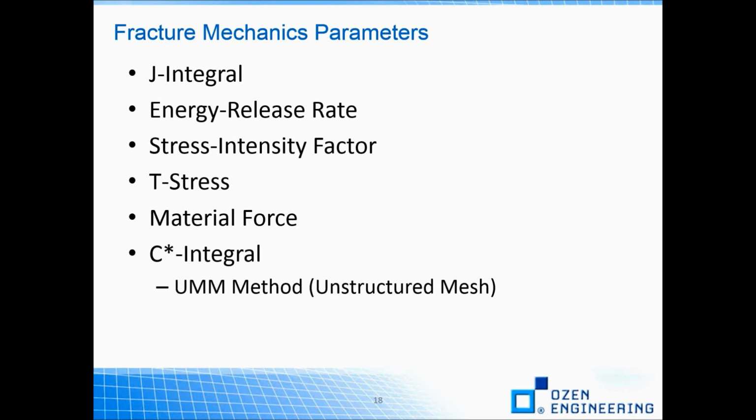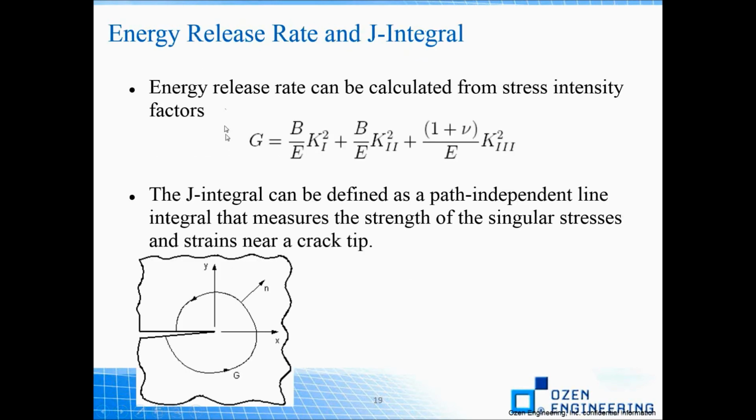I have listed here the UMM method, which is the unstructured mesh method, which is not actually a method for fracture mechanics, but for finite element analysis to make use of unstructured mesh available for fracture mechanics parameter calculations. Otherwise, it's known that the above methods strictly require structured mesh to calculate those fracture mechanics parameters.